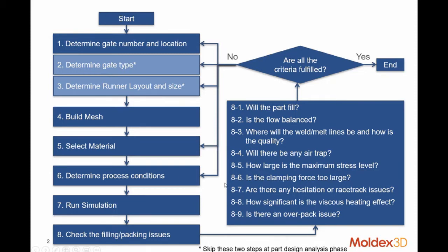If you look at your warpage results first, you're going to be biased and you're going to be trying to figure out why a certain phenomenon occurred. You should get an idea of what you should be seeing in the warpage before looking at the warpage. It'll help you out a lot, and it'll answer more questions than just looking at the warpage results alone.